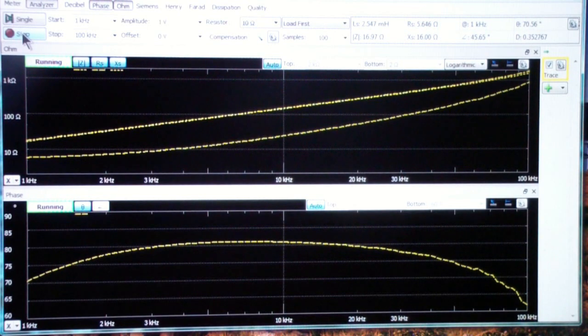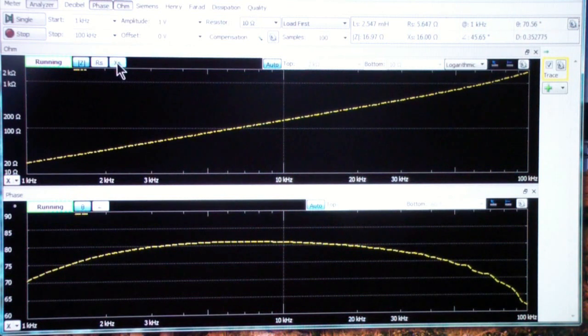It goes up with frequency. And let's just look at just the impedance of the primary. And if we went and measured the secondary and looked in reverse, we'd find the same thing is true, that we would have some resonant points if we drove the secondary, because a transformer is relatively symmetric.